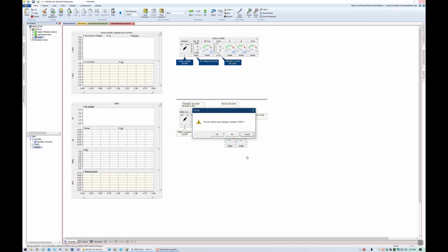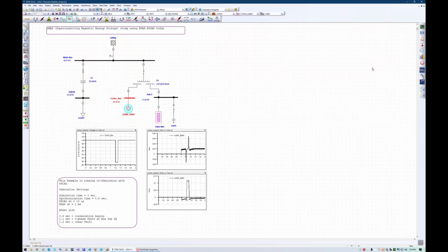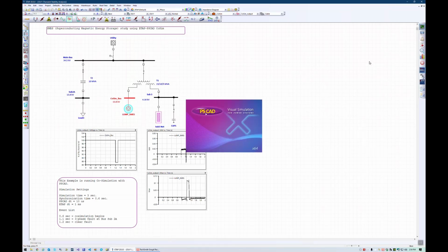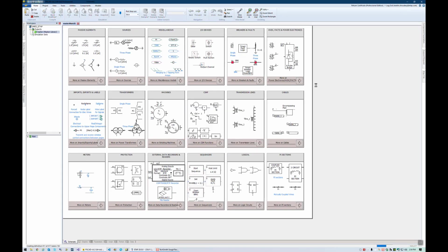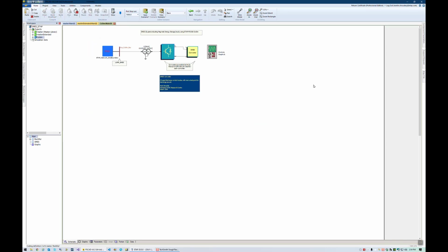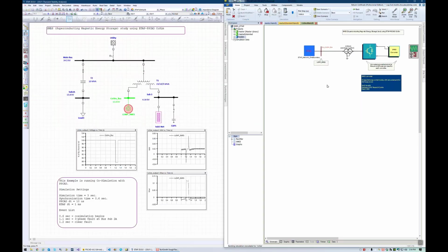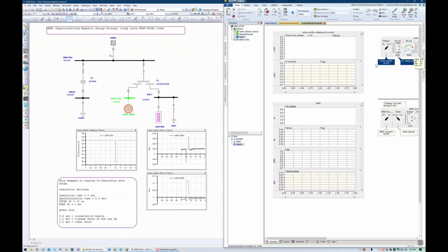Now let's start the CoSimulation. We have to close the eMTP domain first. We go back to ETAP and click the Run Transient Stability button as normal. When we do this, ETAP automatically starts both engines and the eMTCoSim engine, which is used to exchange data between the two separate domains. At this time, both engines are running together and exchanging data.